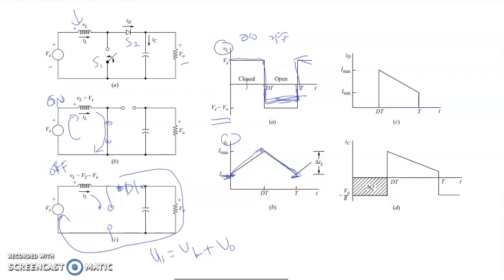What happens is that when you switch on, it charges up your inductor. When you switch off, the polarity will change. Just now, the current flows into the inductor, positive and negative. But now the polarity changes, and here becomes positive, so it builds up in terms of voltage and returns to the circuit, to the load.